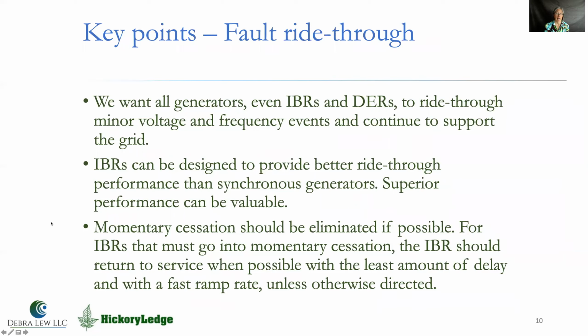And then, as NERC points out in their guidelines, we should really eliminate the momentary cessation if possible. If you have IBRs that are going into momentary cessation mode, then you should try and minimize that impact as much as possible by getting them back into service and getting them back up to full output as soon as possible.